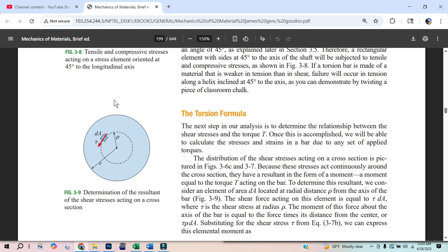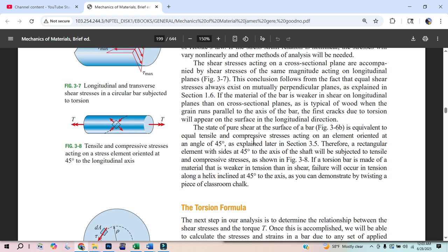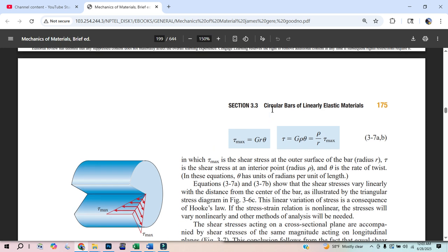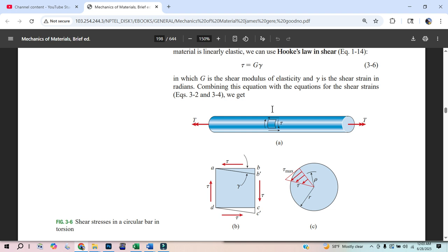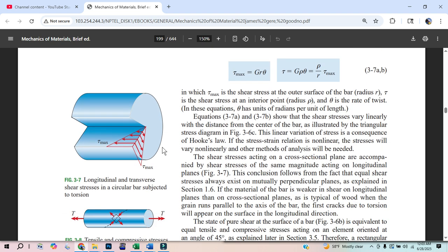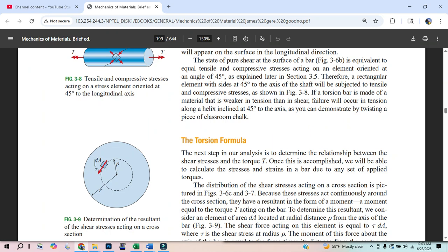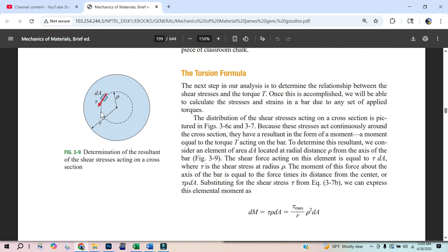Even for me, I've tried to make 3 or 4 videos, like one a night on this topic, and I'm always getting just a little bit tighter, you know what I mean? Just like, oh no, that's the more important thing. And for this one, it was like, wait a minute, this value drives the integration equation. When we come down to here, this value for shear stress is what we need to know, and then we're going to know that stress acts on a little piece of area. That's going to be a force. That force is a distance rho away. That's going to be a torque, but that's just a little portion of torque. And then we have to sum all the torques about that circle.